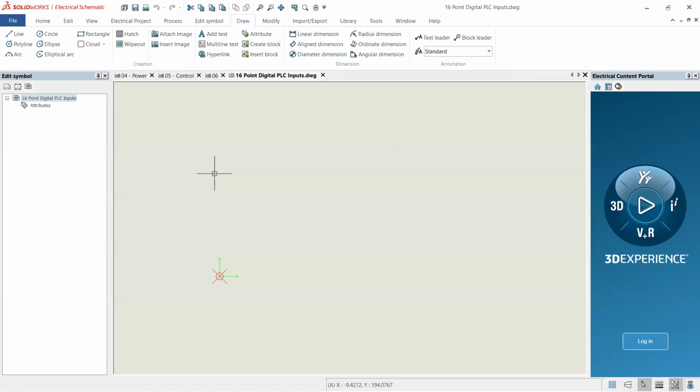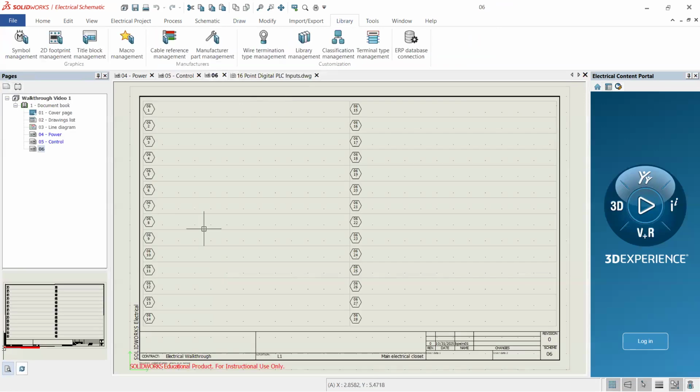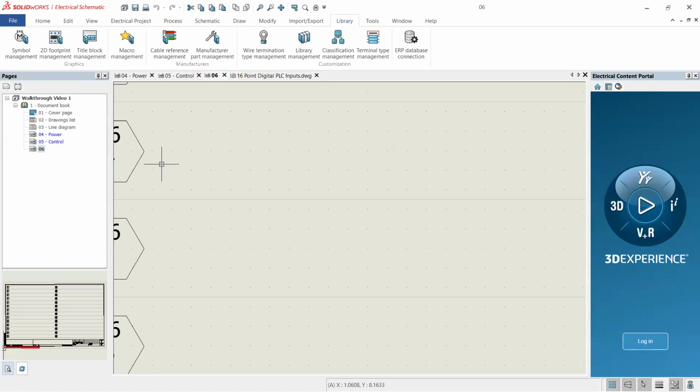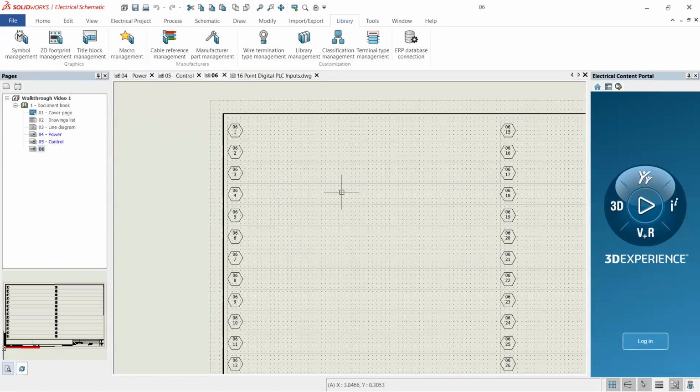When we draw this thing, multiples of 2.5 seem to work very well. And if we stick with that, so 2.5, 5, 7.5, 10, that kind of thing, that lines up basically with this dot grid spacing on our scheme so that all of our wire snaps will work correctly when we go to throw it in here.